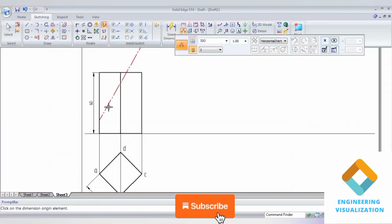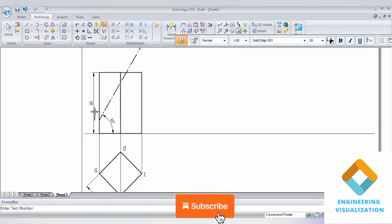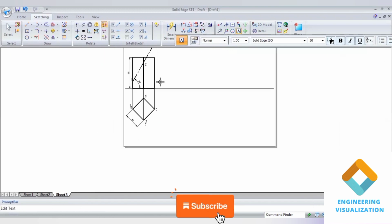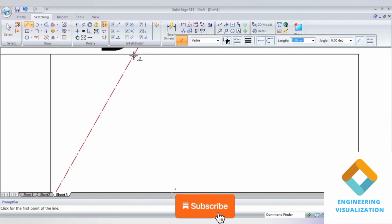Now we can show the angle for this section plane. The angle of inclination is 60 degree. Now we can give the naming here. Point 1 is where it is cut, on the A edge. Point 2 is falling on the vertical edge B. And then point 3, you can see it is not falling on C, it is falling somewhere in between B and C.